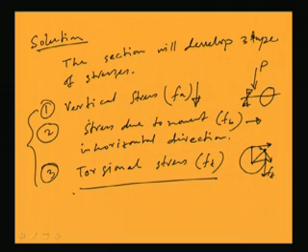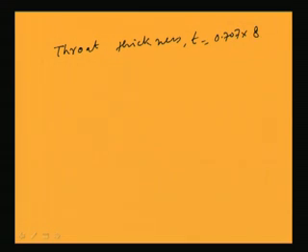Then we can find out the maximum stress where it is coming, and accordingly we can find out the allowable load. Right. So, what we will do? First we have to find out the throat thickness. So, throat thickness will be 0.707 into S. S is nothing but 8 mm, it has been given. So, this is coming 5.656 mm. So, we have the throat thickness.